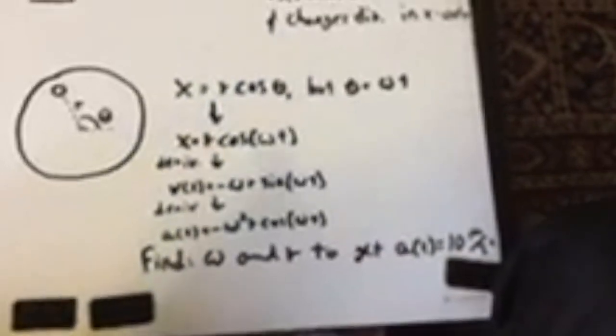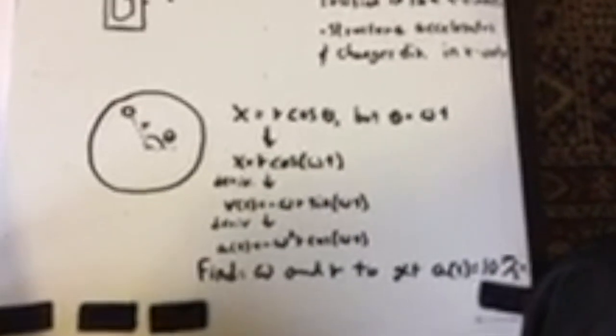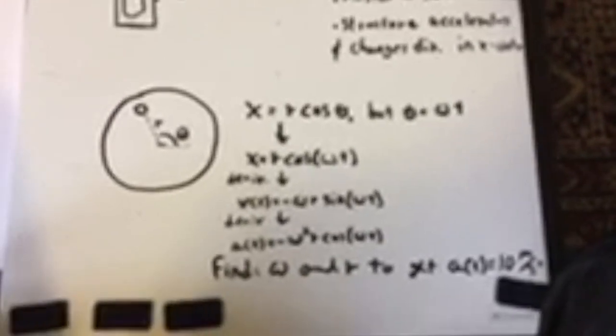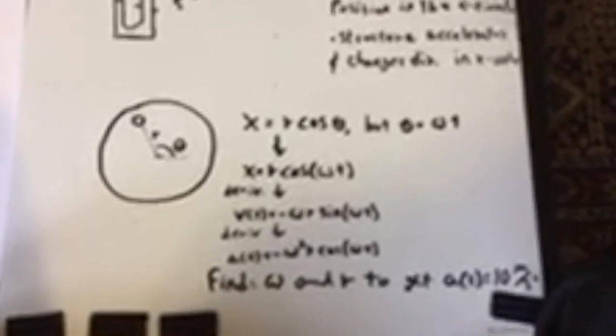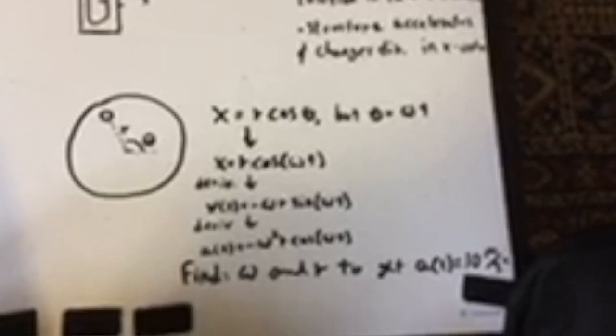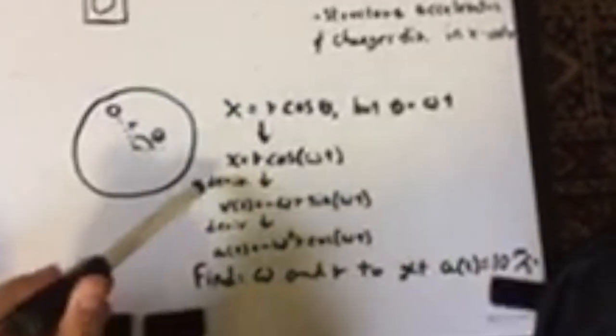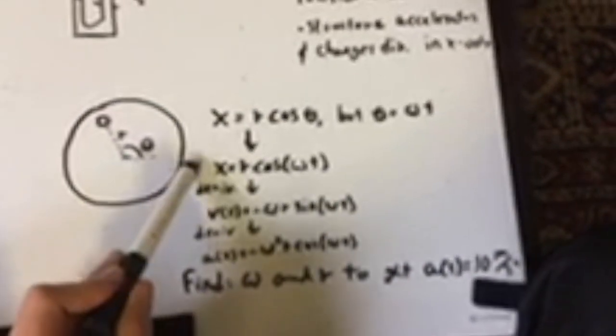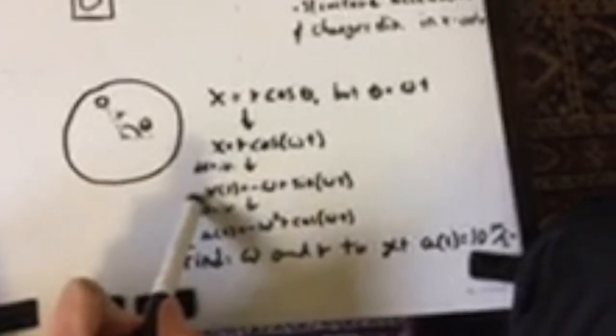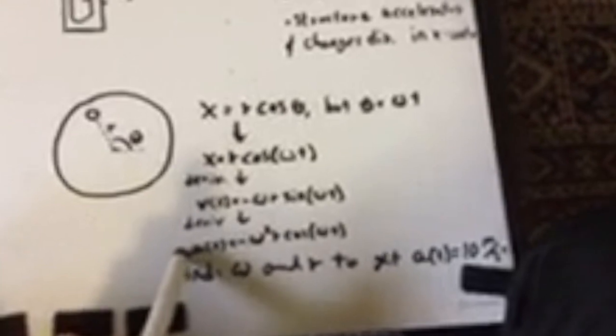And in order to find the acceleration, which is ultimately what we're trying to solve for, and then ensure that we set equal to more than or equal to 1g, 9.8 meters per second squared, we derive the position formula for the position of the peg and the structure in the x direction. We find the velocity, and then we take the derivative again in order to find the acceleration.